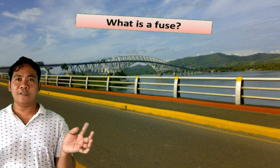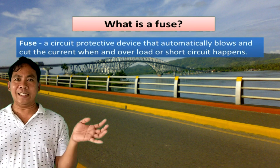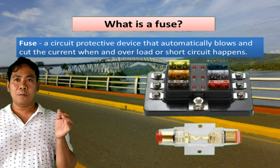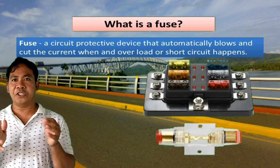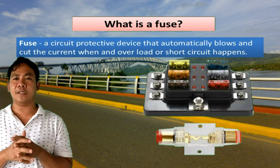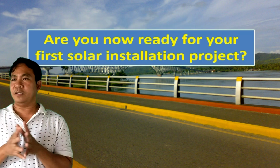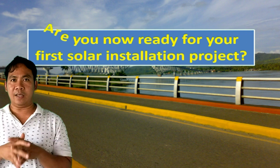So another is the fuse. What is a fuse? A fuse is a circuit protection device, like a circuit breaker. It is an electrical device that automatically blows and cuts the current when an overload occurs or a short circuit happens. There are many types of fuses. The only thing is that when a fuse burns, you replace it with a new one, while a circuit breaker you can only reset.